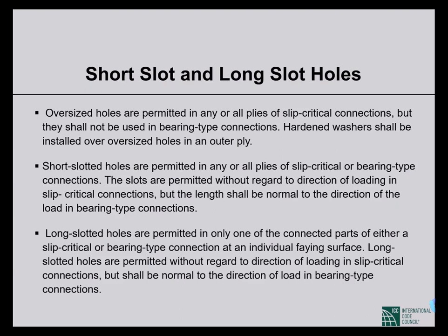For slip critical connections, if we have oversized holes, then for the washer, in the code there are specifications of standard washers. I didn't cover those, but there are specifications for standard washers, fasteners, and all the accessories. So for oversized holes, we cannot just use a standard washer, we need to use hardened washers.